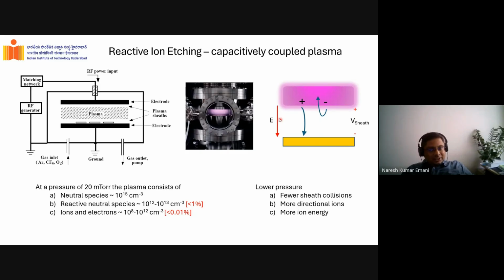Okay. One of the ways to monitor the density of plasma is to use what is called optical emission spectroscopy. You're seeing light, right? Put some of the light in a spectrometer. Look at the strength of the peaks. You can get the composition also to some extent, and you also get the strength of it. Yeah, the brightness, but brightness with some spectroscopic information at what wavelength you're having the brightness.